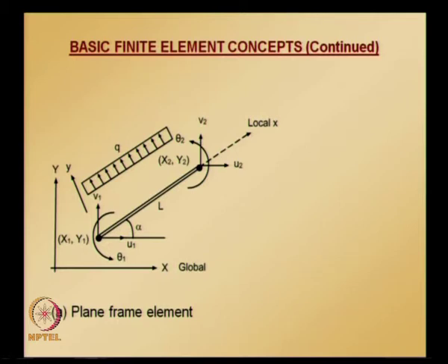Local x axis is defined by a vector going from node 1 to node 2, and local y axis is perpendicular to local x axis, or at 90 degrees counterclockwise from the local x axis. The applied forces and moments are assumed to be positive along global coordinate directions. The distributed loads applied over an element are positive if they are acting in the positive local y direction.